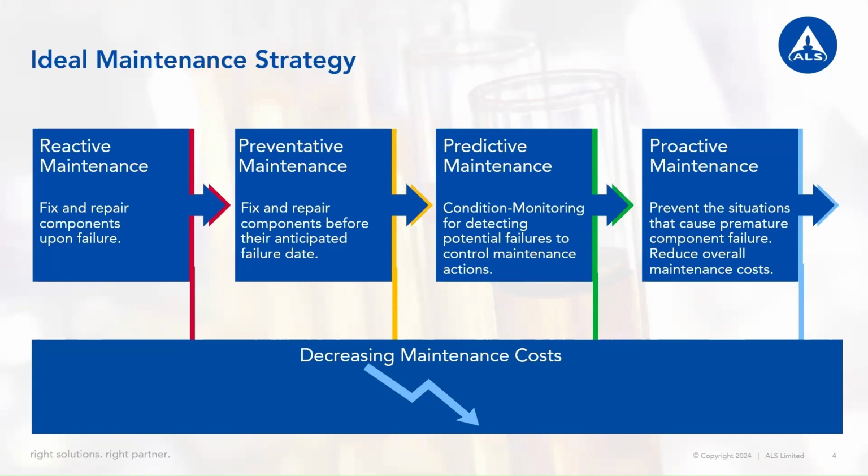Reactive maintenance is simply fixing something as soon as it breaks down. This is primarily what many businesses use and is the reason why maintenance costs can be so high. Expensive part orders, unplanned downtime, and undelivered targets can all stem from improperly monitoring your equipment. It can be useful, but only when it is relegated to low criticality, cheap to replace equipment.